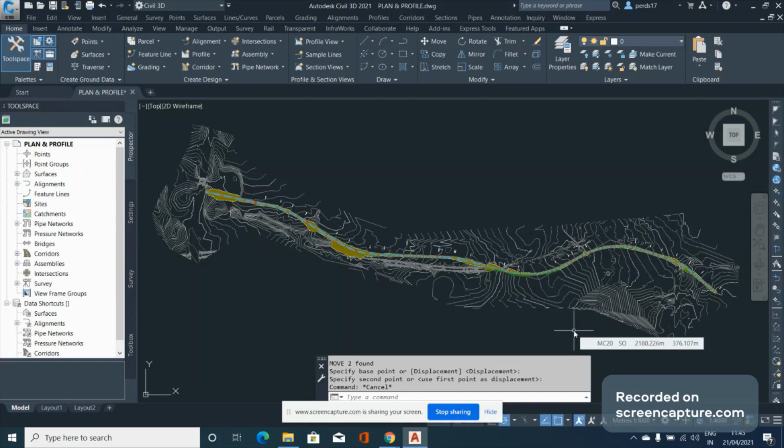Second, you need to have a DST file, the sheet set file, where all your information is saved. If you have to change the drawing name or drawing number, you don't have to go into each individual file. You can change those using the DST file.